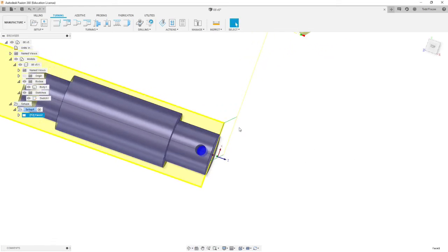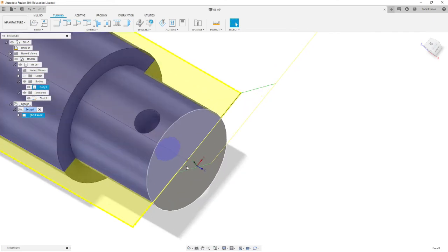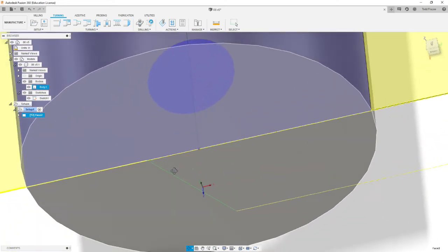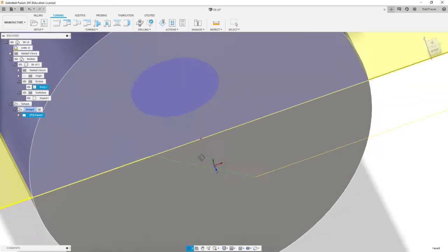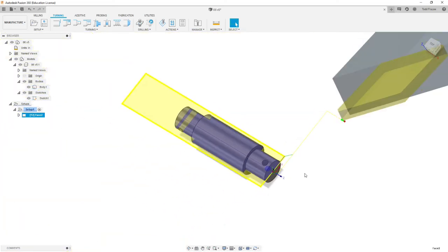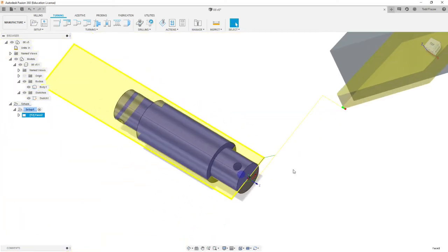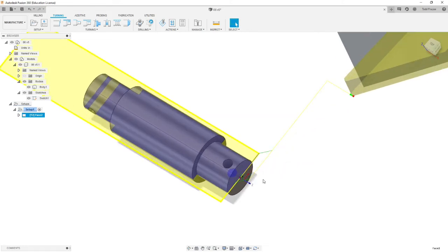So our tool path has our 45-degree lead in. It's cutting it where the stock starts, and then it should be going a little bit past. That was probably too much for a small part like this, but that'll ensure that we've cleaned up. Now on that side of the part, it's really going to be rubbing on the non-cutting edge of the insert.